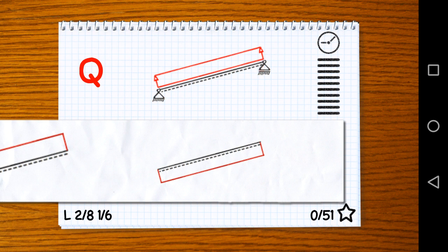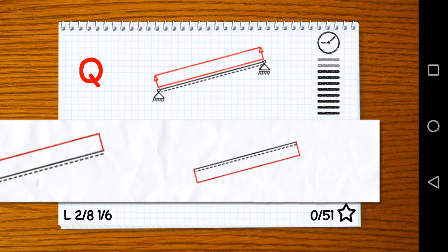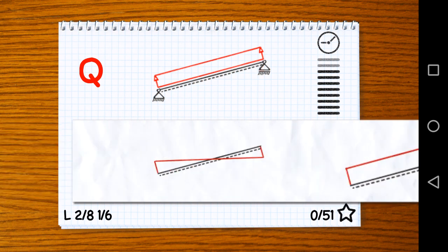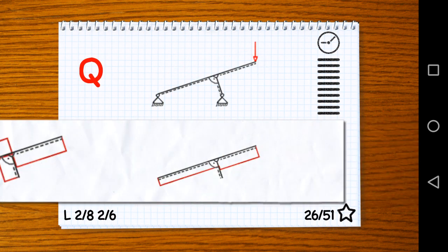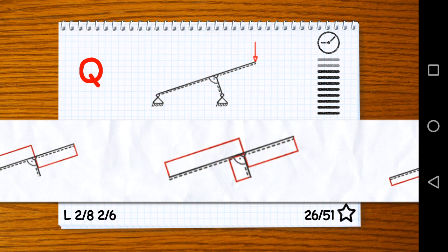Good. Looking at the beam from the right to the left, we should have a linear distribution going upward. Linear distribution going upward from the right to the left. That's our trick. Looking at this system too, from the right to the left, we need to have a jump downward first, so a jump to the positive values. Okay, all of them are doing that.